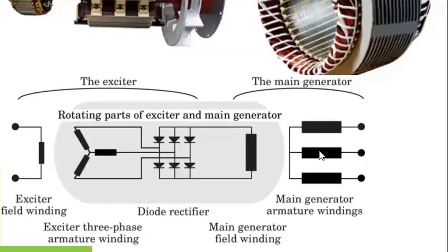The resistance you get between line 1 and line 2 should be the same between line 2 and line 3, and also between line 1 and line 3, because you are taking the resistance of similar coils.